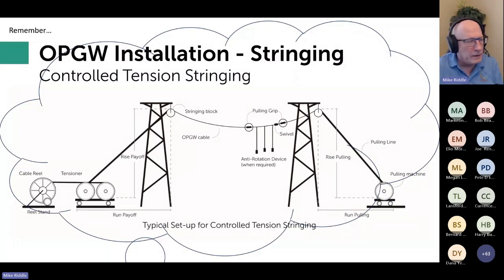with no problem. If it's moving less than that, or if it's obviously tight like a banjo string, you need to loosen up. How can you loosen up? Often, if there's a braking mechanism, that's obvious. Turn down the braking mechanism. If there is no braking mechanism, it could mean that the axle is just not rotating freely, which you'll have to take a look at and deal with. Sorry, I don't have an easy solution if that seems to be the problem.